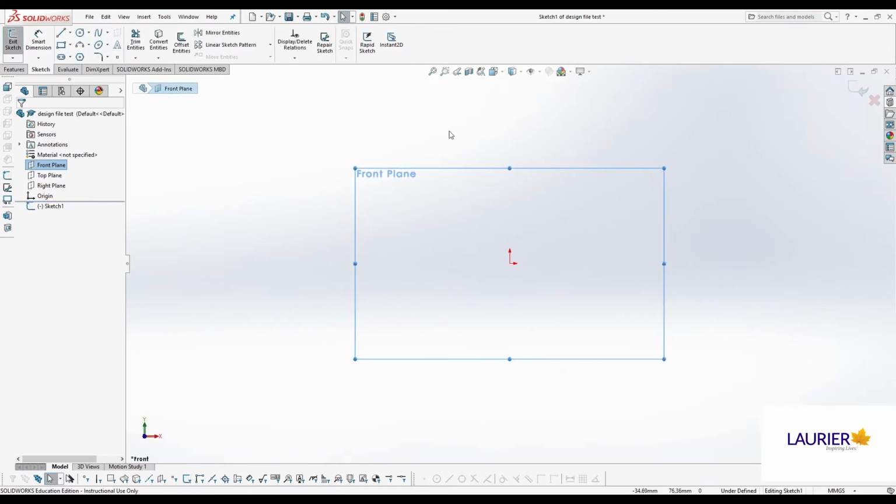You'll see that as soon as we do this, the CAD has kicked over into sketch mode and has activated the sketch. So you can see in the upper left that sketch mode is active. SolidWorks has recognized that we want to do a three-dimensional object using the extrusion tool. So to do that, it knows we need a sketch, and then we need to extrude it. So it's kicked us over into sketch mode. We'll make our contour. We'll then leave sketch mode, and we'll come back into the 3D mode, and we'll do the 3D operation at that time.